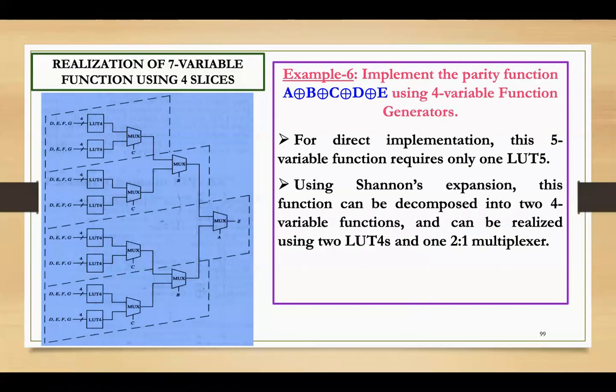Fine. So the same thing can be reduced. You can take this equation as an example, and you can take the expanded version of this equation, and you can use Shannon's decomposition theorem, right? Based on the number of LUTs asked, you can implement it. So if 7 variables are there and you want 5, then you'll be taking 2 variables outside. And if 2 is there, then it means it's only 4 combinations, 0, 0 to 1, 1, right?